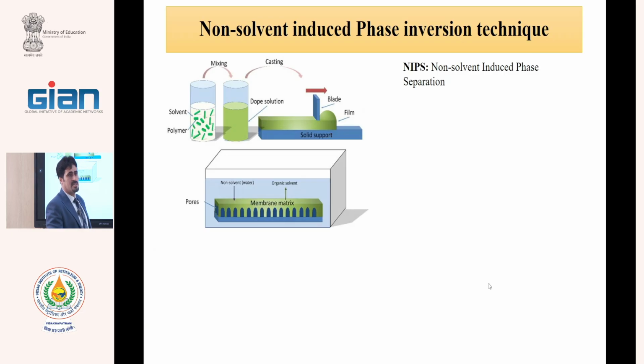This dissolving mostly needs 1 day. After addition of polymer to solvent and mixing, usually we need 12 hours, but in the lab we use 24 hours, 1 day, for completing dissolving and reducing the gels. I should say that some polymers cannot be dissolved and form gels.